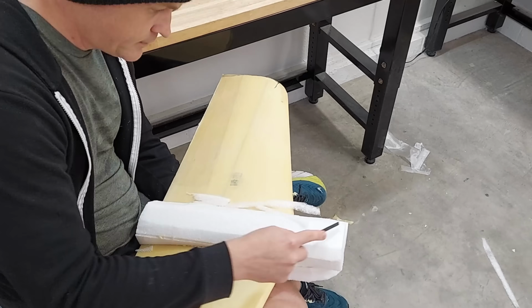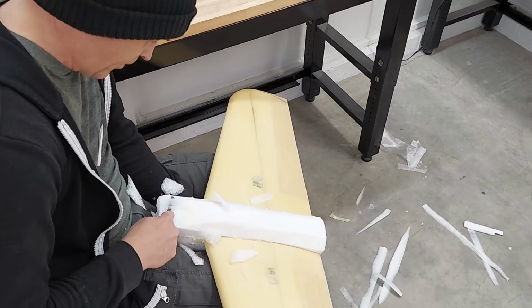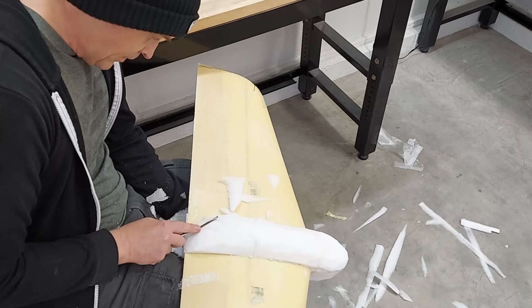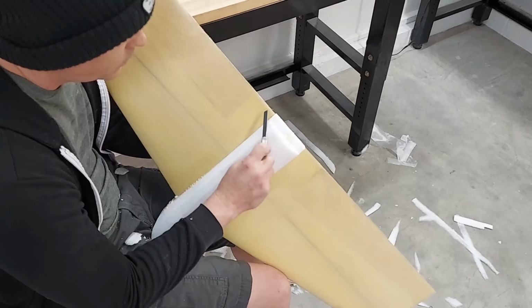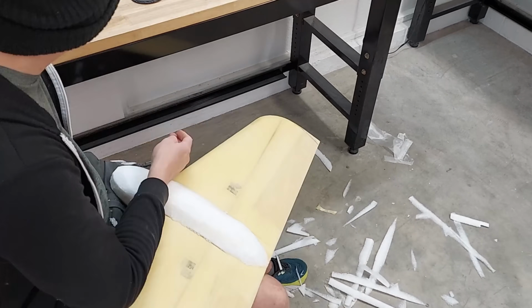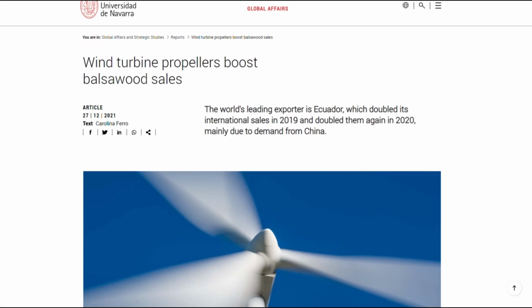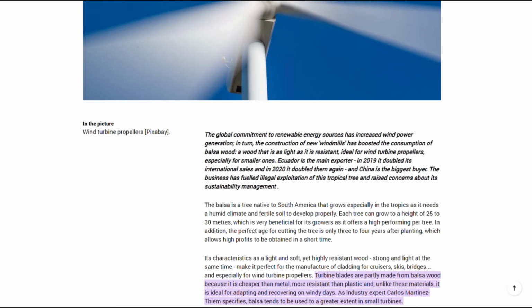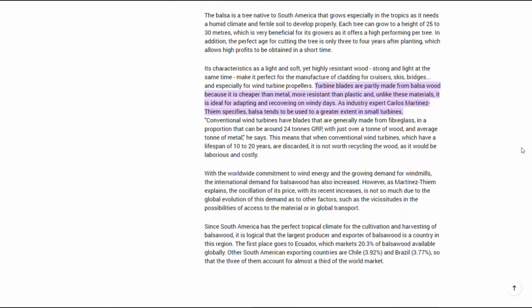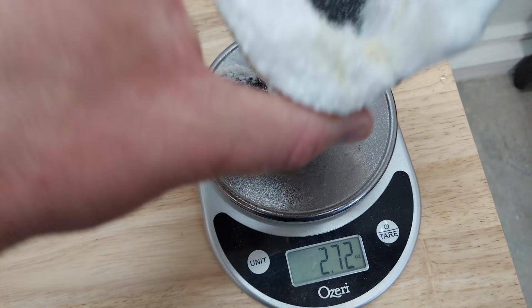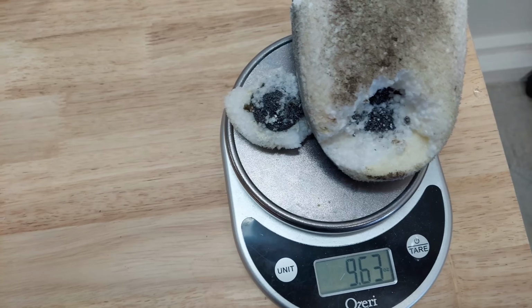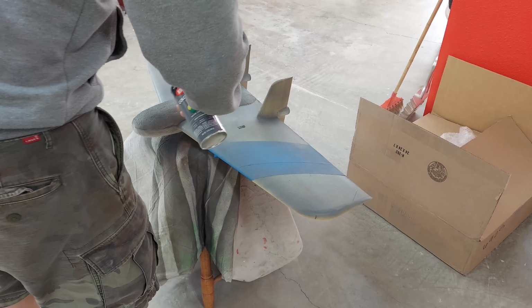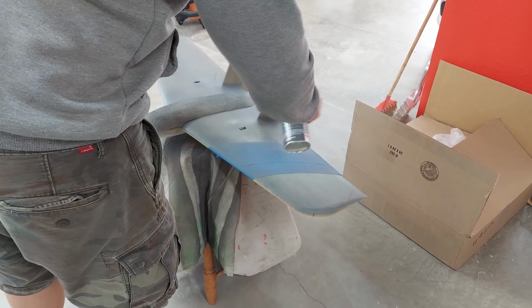I needed a fuselage to get the weight far enough forward to demonstrate a normal flying wing configuration before moving the weight back to an unstable configuration. I really underestimated how long the nose would need to be as the balsa elevons were really heavy. Not only is balsa wood getting very expensive, the weight is also going up dramatically as most of the high-quality wood is going into windmills. I ended up adding about 8 ounces of lead shot to get the plane to balance, which is a lot on a 32-ounce airplane. Paint is mandatory on all my aircraft. If they don't look decent, they won't fly decent.